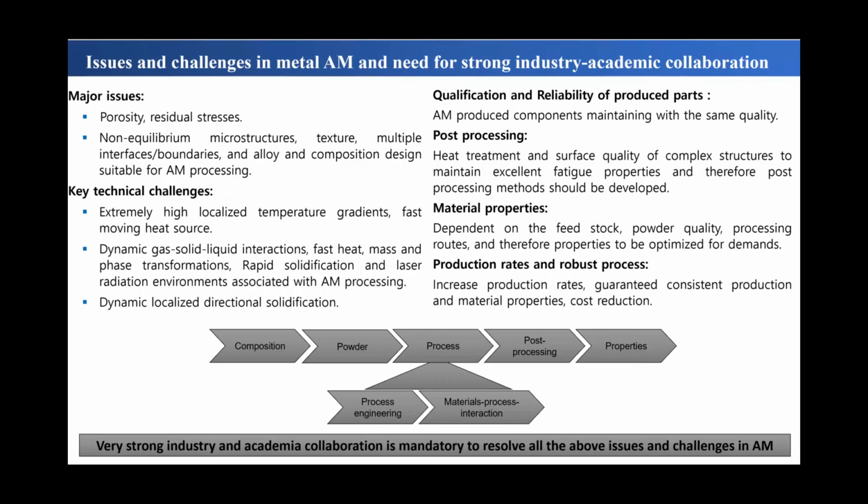So far, I can enumerate the challenges which the metal additive manufacturing industry has, and for which there is a need for a strong industry-academic collaboration. The major issues to be tackled are porosity and residual stresses, which are detrimental for components which are supposed to be loaded, whether under uniaxial loading or in cyclic loading.